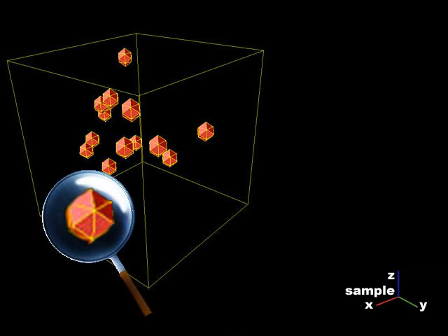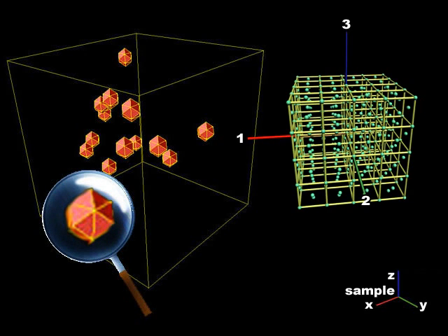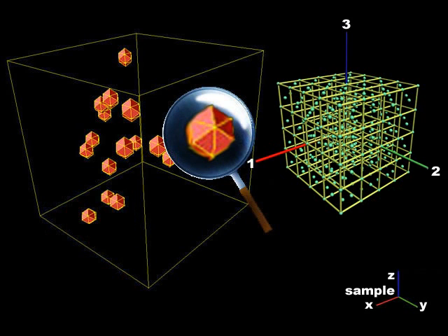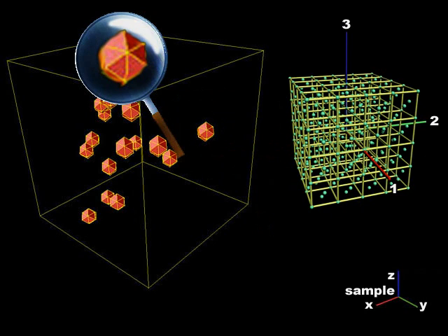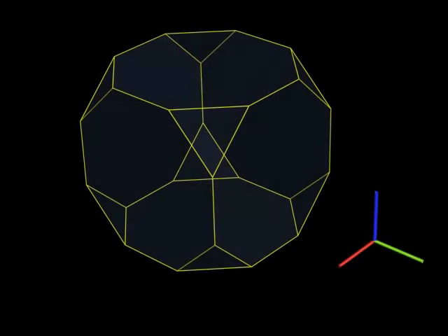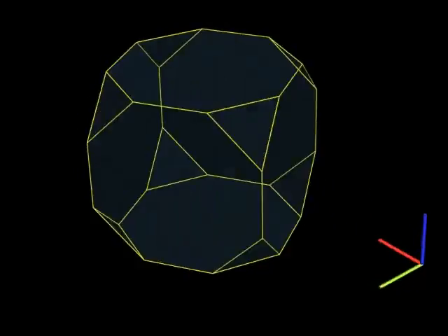A closer look at each grain reveals the lattice structure. Note that the lattice orientations differ by only a rotation about the Z axis. To help interpret simulation results, we wish to plot each crystal strain as a function of its lattice orientation. The Rodrigues box is a three-dimensional orientation space that helps to visualize the orientation of the crystal lattices of simulated grains.